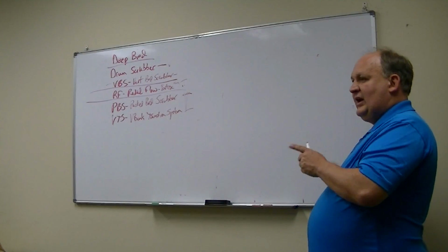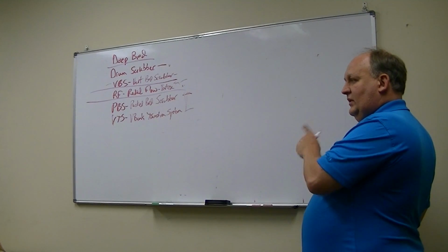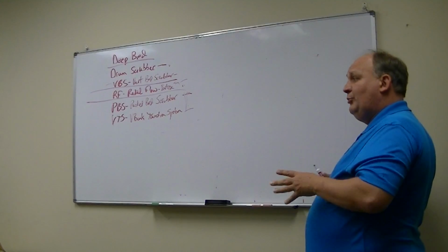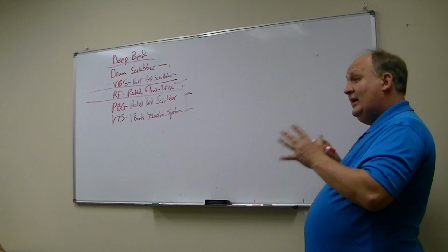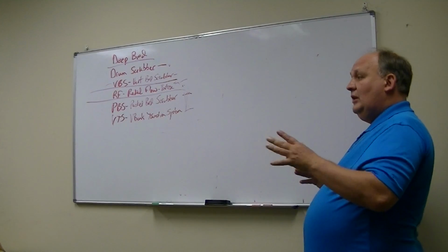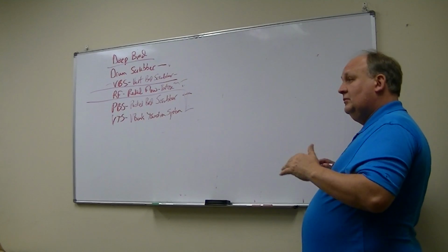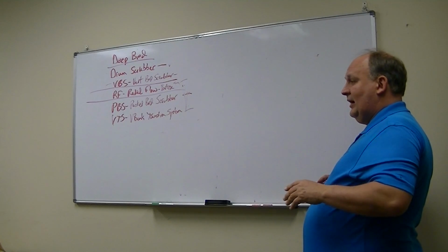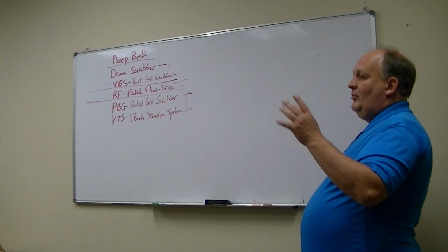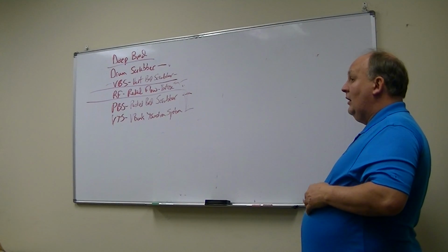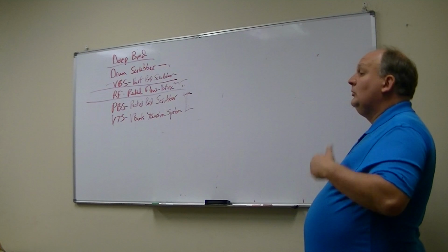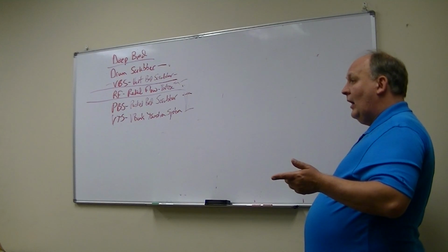So that's Fill-Chute design. Very, very important for these units. And it's very important that we tell the client, the contractor who's installing this, that 2 weeks after you fill this unit, you need to go back and top the system off. Document it for them and everything, because when we get that call a month or two down the road and they say, hey, your system's got odor coming out of it, we'll say, well, you remember when I told you to make sure to top off the media, and they go, oh, yeah.